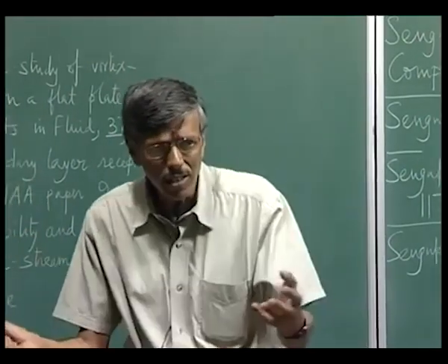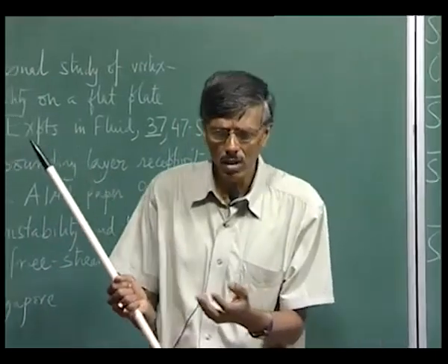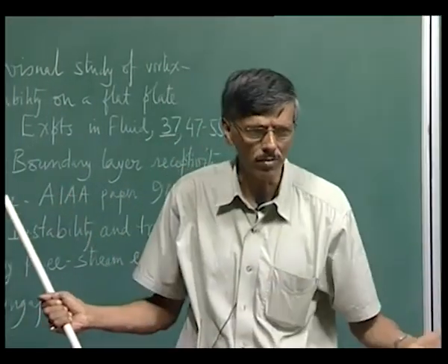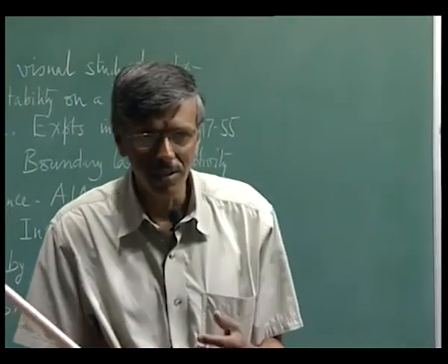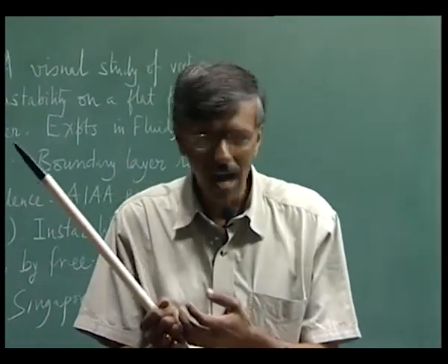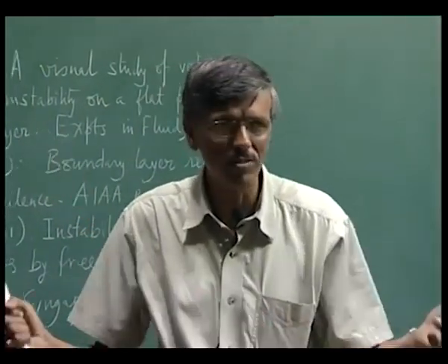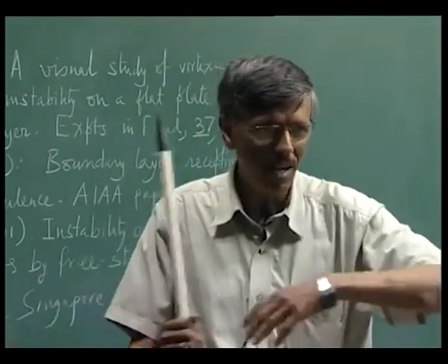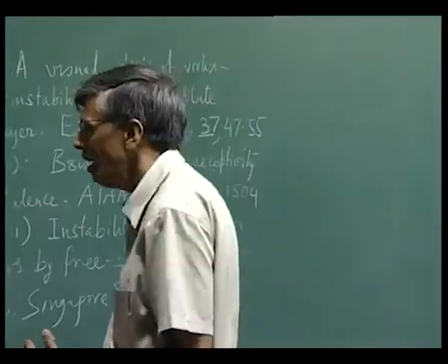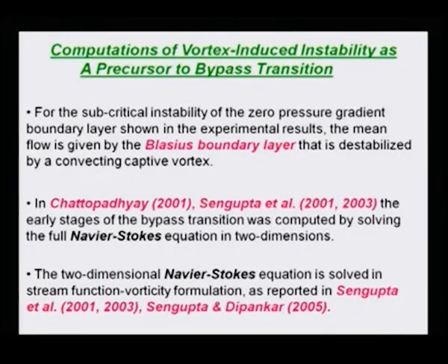So, eventually all of this takes over, and we have seen from the experimental evidence for case 1 that it just happens in a very violent manner. Once it appears, it just takes over and spreads over the whole domain, and you see a massive mixing. So, this bypass transition mechanism that we are talking about is a very potent one.